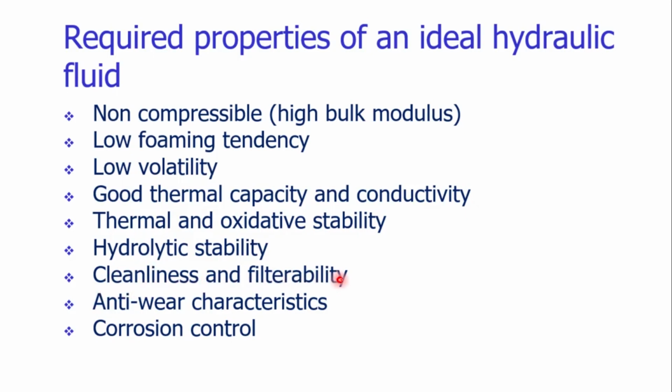The fluid must be clean and it can be easily filtered. The hydraulic fluid should provide anti-wear characteristics. It should provide good lubricating characteristics. It should be non-corrosive. Generally, the hydraulic fluids corrode the mechanical elements, the ferrous elements of the system, and we need to continuously monitor the condition of the hydraulic elements.